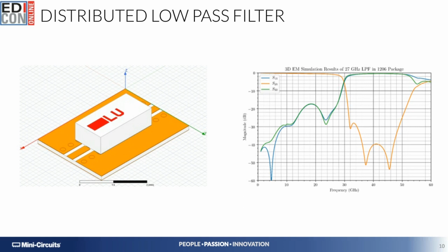these simulation plots. These simulation plots also show much deeper and broadband stop band rejections, sustained performance at frequencies beyond X-band, and we may actually provide surface-mountable shielding structures to alleviate some of the needs that are required for deep stop band rejections at very, very high frequencies, above 30 gigahertz or so.